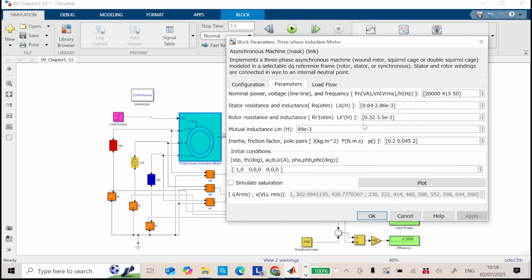We did that before for the M code. When you add extra rotor resistance, the starting torque increases. But the maximum torque stays almost the same, because the slip for maximum torque depends on the rotor resistance, but the maximum torque itself, to some extent, does not depend on the rotor resistance. R rotor over X equivalent gives you the slip at maximum torque, while T maximum equals 3V squared over 2X equivalent. That is if the stator impedance is neglected.